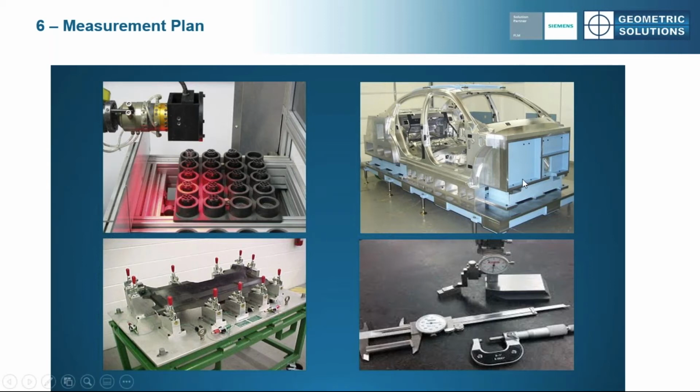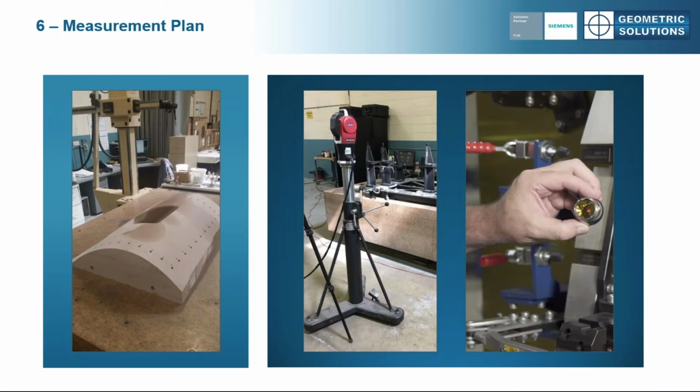If I look at this one up here, this happens to be a perfect body that is made and machined for the sole purpose of doing the interior. So they actually can check to see if there's a problem with the interior because they got a perfect buck for all the pieces. And then I got hand applied, those are very cheap, but they're not as fast or not as reliable, and depending on the complexity of the part, may not work at all.